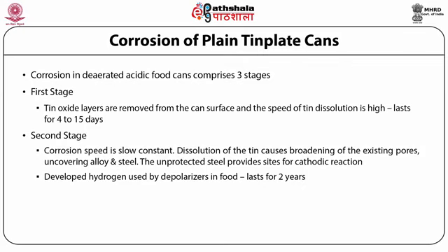The third stage is shown by a high rate of tin and iron dissolution. As large areas of steel are exposed, hydrogen is produced at a faster rate and accumulates in the can, causing swelling.